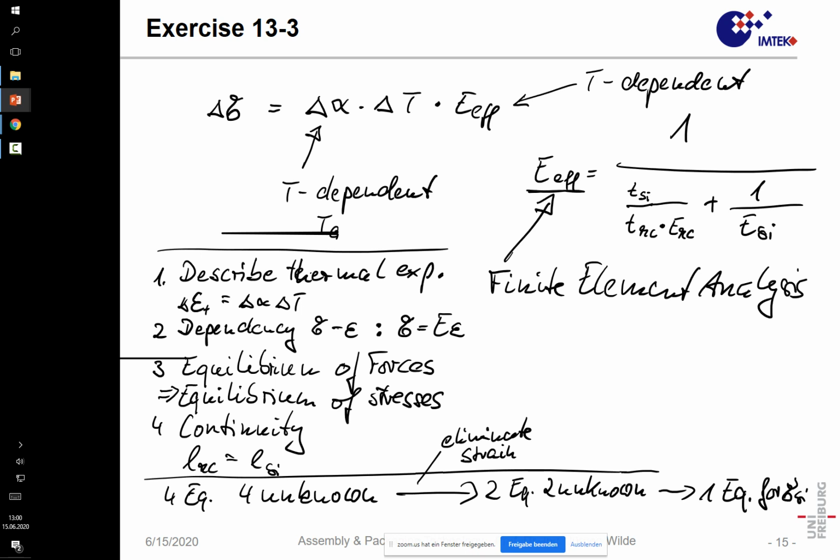In that case, again, we have delta alpha, delta T. Or, in fact, this should be written as T times delta alpha plus alpha times delta T. And in that way, if we would have a homogeneous body, then it would be relevant that we have a homogeneous CTE multiplied with the temperature difference, and again, that gives us a strain difference which acts as an elastic strain. Okay, so we are finished now.